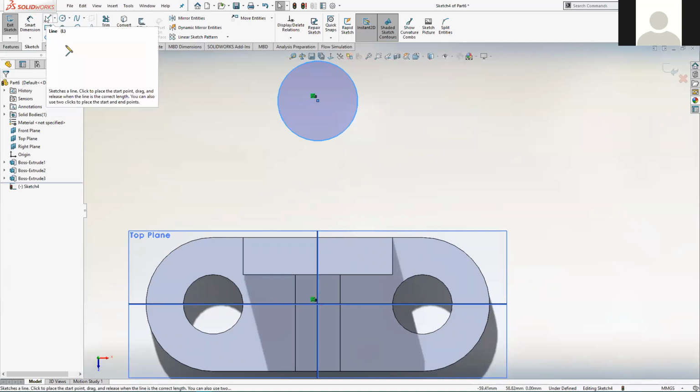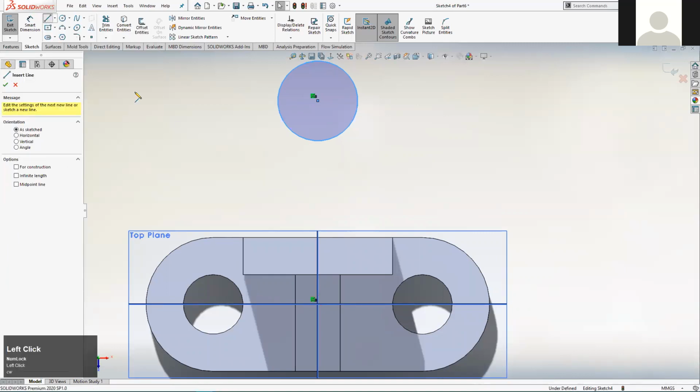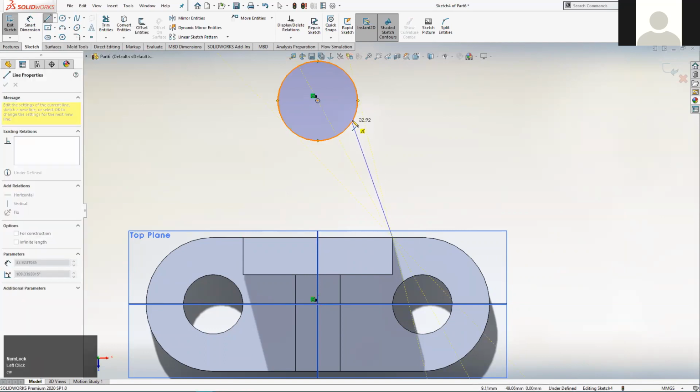And then I'm just going to get the line tool and draw a line that starts at that point there, so it locks itself coincident with that. Again, we talked about this. There are three options here. Either this line will lock itself to anywhere on the circumference of this circle, so that's that one. It will lock itself to 3 o'clock on that circle, horizontal on the circle there. That's not what we want either.